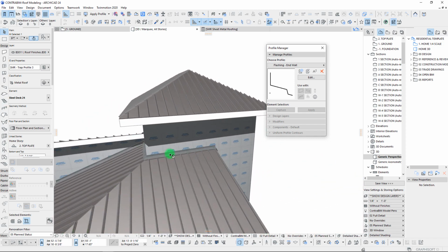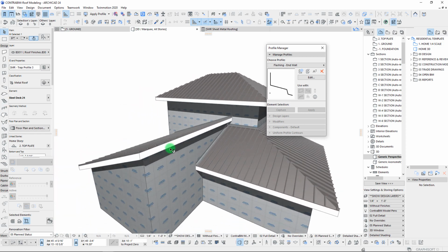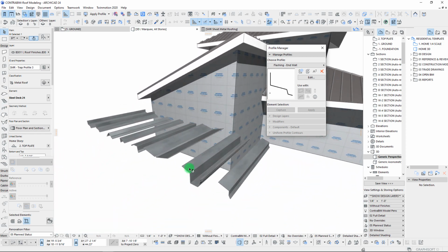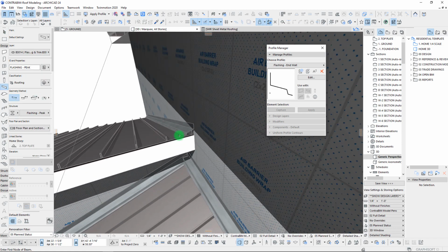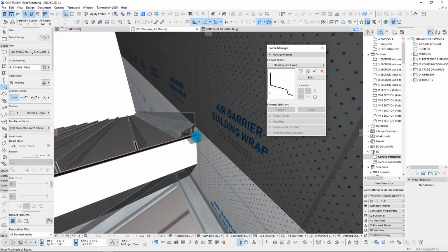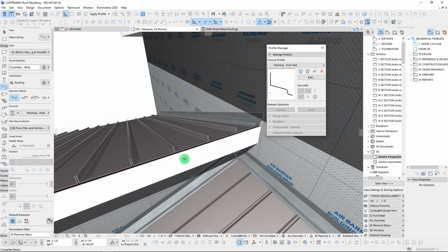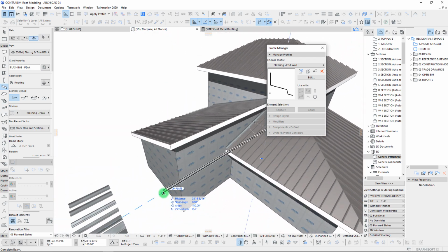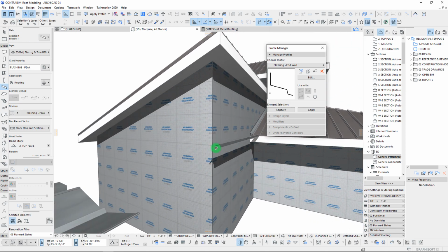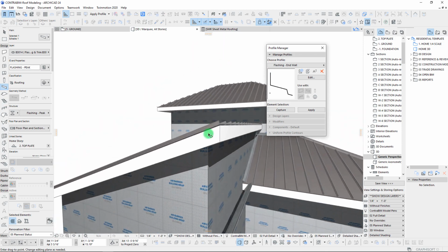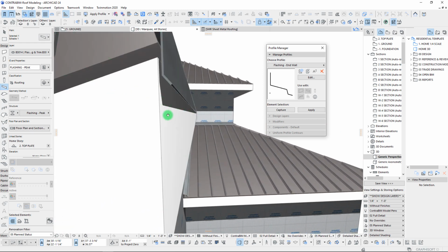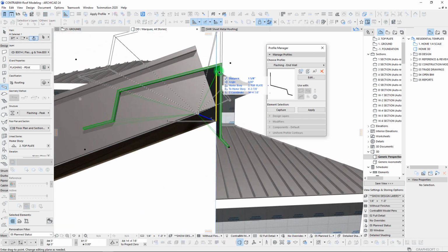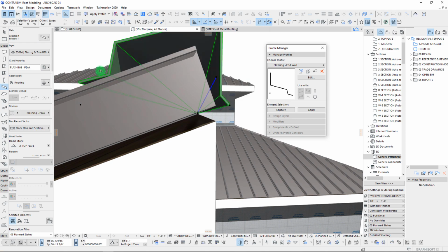We have our end wall connection. Let's work on our peak right here. Let's go through. We will pick up our peak beam, and then once again we're going to start it right from this point. We can see that it's already set down. So in this case we can model it from that low point, and then we'll take it here and elevate, and we can continue to elevate this just a little bit higher so that we're sitting right on top up here.